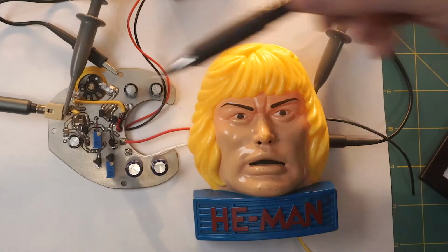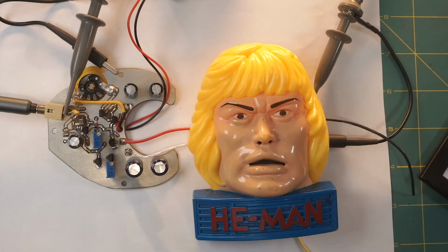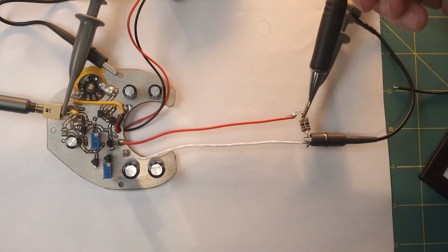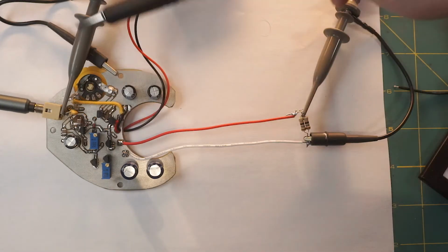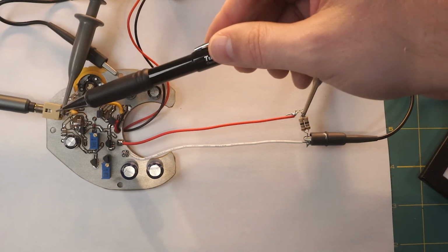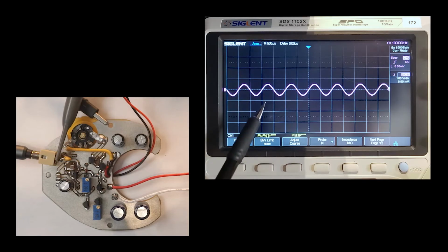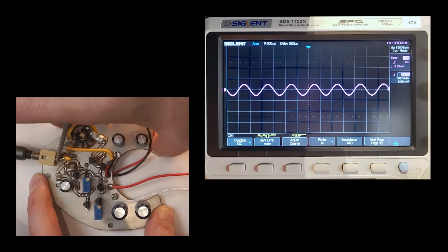Okay, a test. Here's the circuit. The auxiliary cord is connected to my signal generator up there, which is outputting a 1-volt peak-to-peak signal. Instead of hooking the output to the speaker, I'm connecting the output to roughly 8 ohms. That way I don't have a speaker screeching at me while I look at the oscilloscope. This probe over here is connected to the input, so we should see the 1-volt peak-to-peak up on the oscilloscope up here, right there. And what I'll do is I'll turn the amplifier all the way up so we're not attenuating any of the signal.